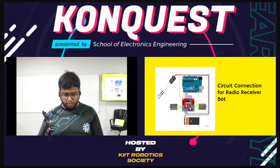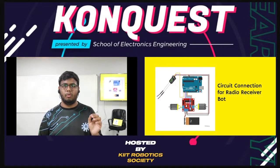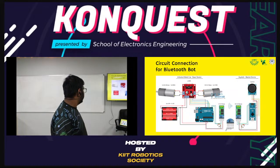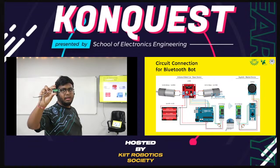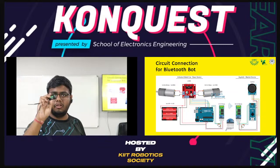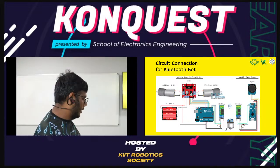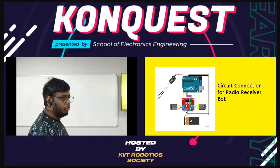But what's the advantage of this? If you make your bot using this type of transmitter, you just have to make your bot the way you would with a Bluetooth kind of transmitter. If you see the Bluetooth part, just change your Bluetooth module with this receiver. That's it. Now the Bluetooth module, if you have used it, uses TX-RX kind of pins. Here, this module only uses the RX pin to transfer the whole data. Just go through the online resources, these are available. So this was the circuit diagram.